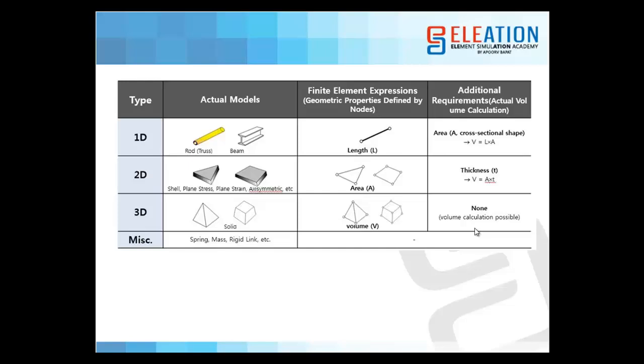So we create the elements along the area, but again we have to generate the entire volume to solve this problem. So we give thickness as an input while we do 2D meshing, after which my software calculates the complete volume, that is area multiplied by thickness gives the volume of that entire domain.